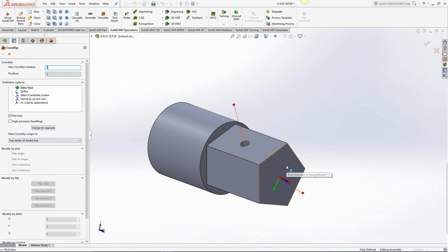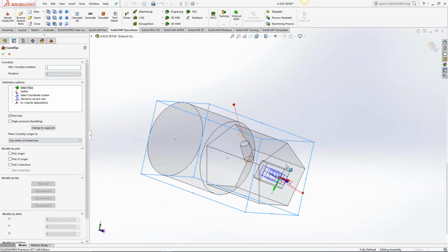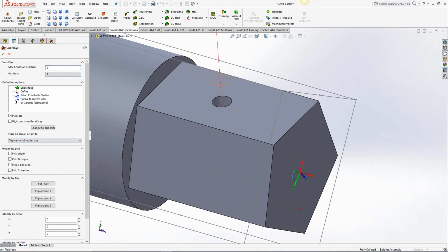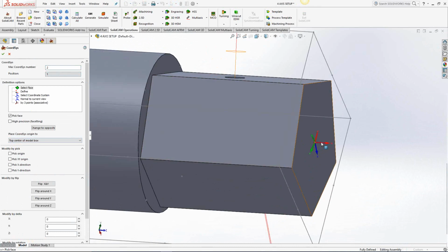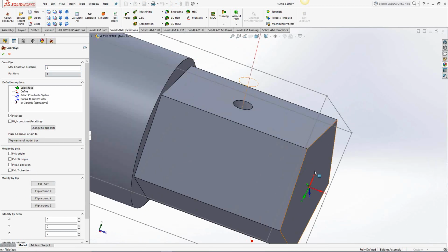This will just find the mathematical center of the part. So let's say I just choose the pentagon right there. You can see our Mach 2 position 1 is overlaid on top of there. It actually is dead center of that part. So that is also a way to tell SolidCAM where the center axis would be, the rotary axis.